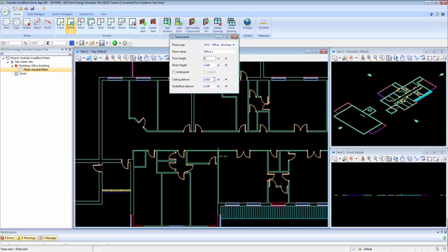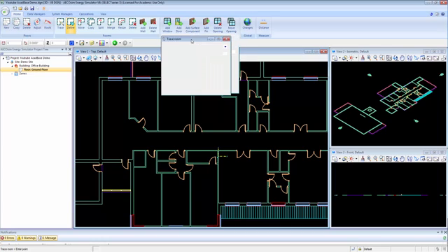It's adjusting the plenums to make sure everything adds up to that 4 meters. Let's say maybe 0.4 underfloor. That gives me 1.2 meters as a ceiling plenum. That'll be fine. We'll leave it at that.